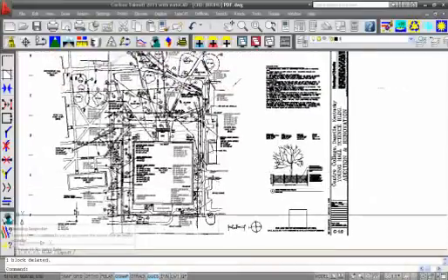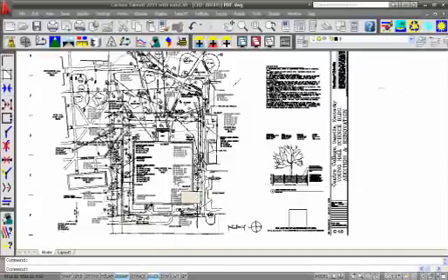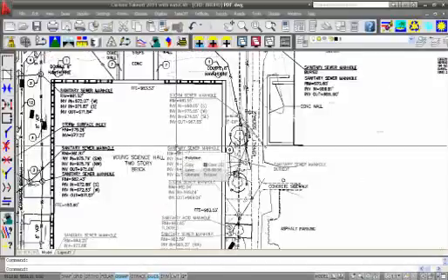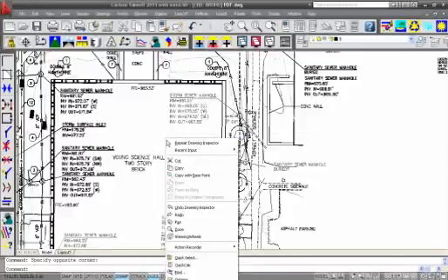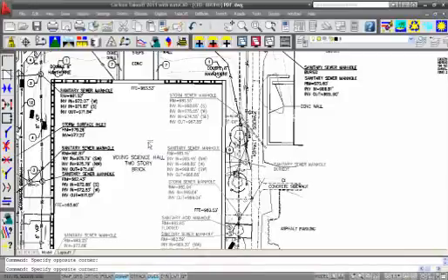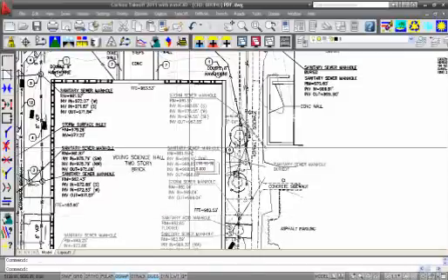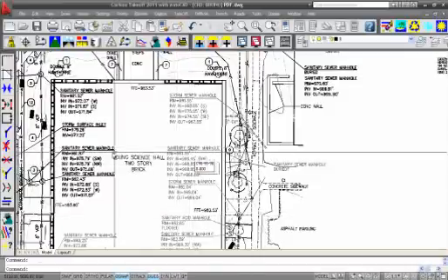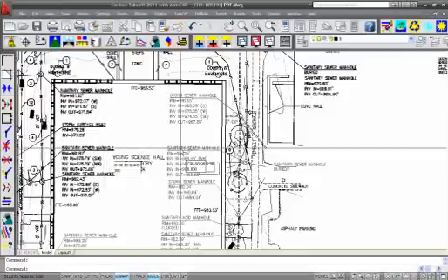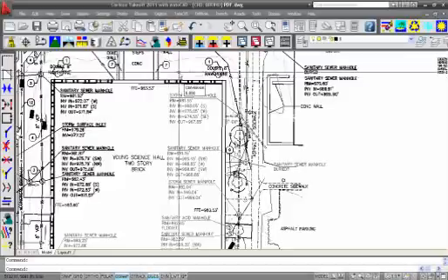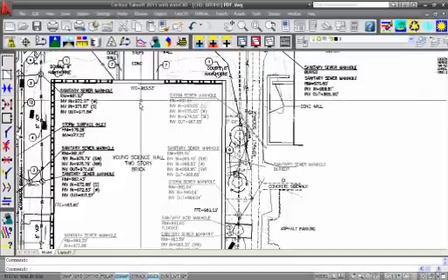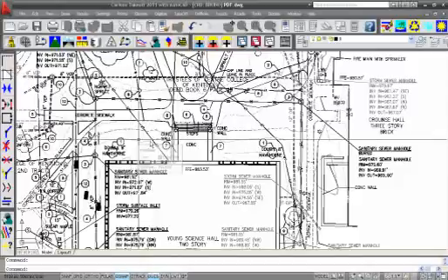And right away, I'll go to Drawing Inspector and go over this line work. And what I have checked for my Drawing Inspector is for it to show me any elevation in the line work, and its layer name. And if I go over here, you can see it's set this to a layer, and this is now on a different layer, black. This is based off of the grayscale. Before, these would all be on the same layer, 0.